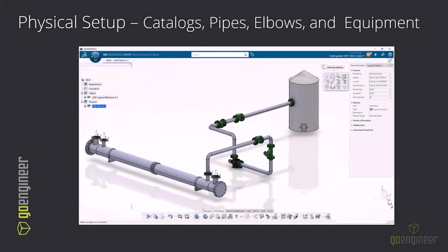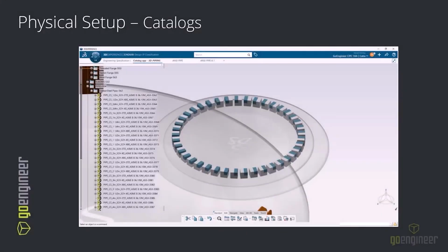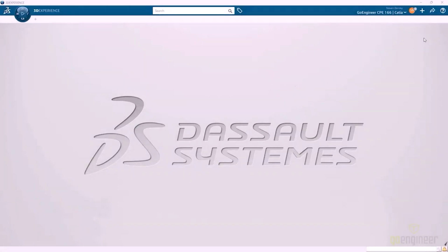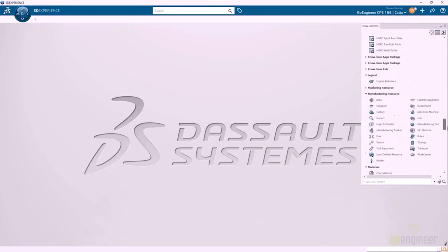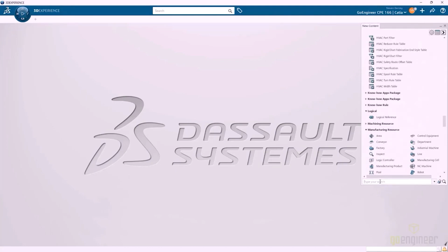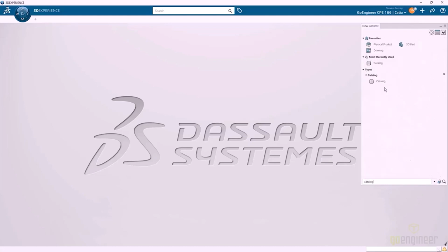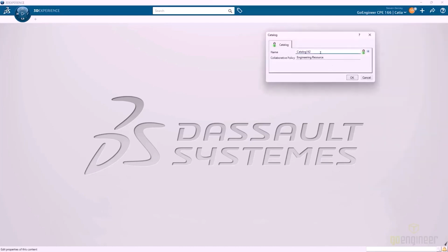So next, let's get to some of the fun stuff, which is the 3D. And we'll start off by creating some catalogs, put in some pipes, elbows, and some equipment. So let's start off with catalogs. So we'll create some new content, and we'll make a catalog. And if some of these are hard to find, you do have a little filter at the bottom, so you can just type in catalog, hit enter, and then there's catalog, so I'm going to start that.